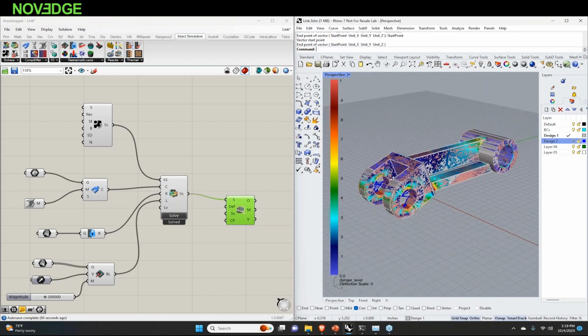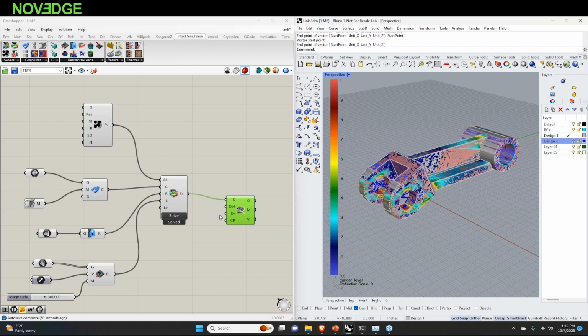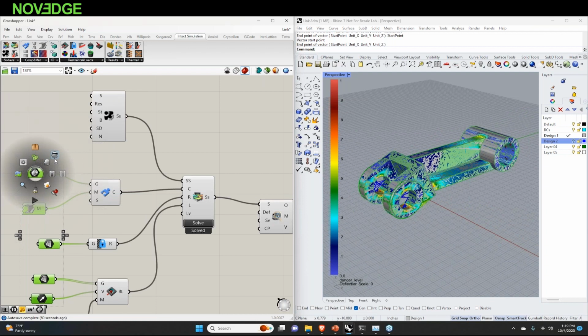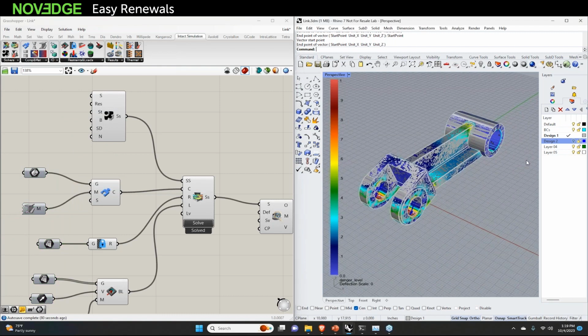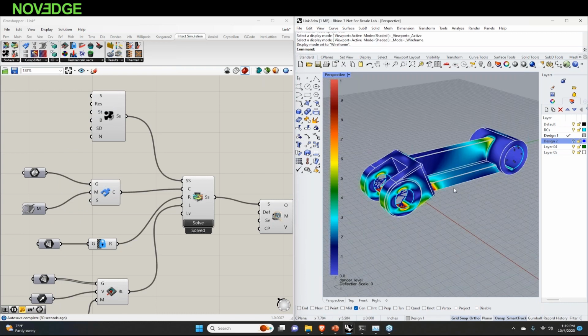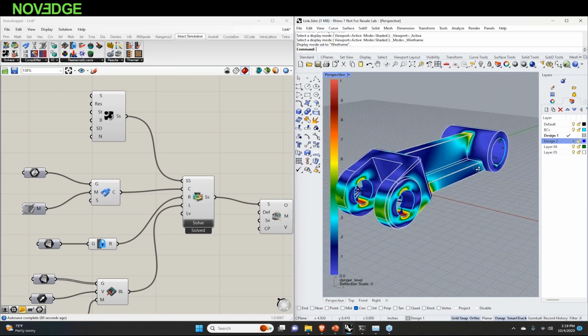And on the right, you see the danger level being displayed on the geometry. What we've also got, it's just an artifact of Grasshopper and Z, we've got some Z fighting going on. So I'm going to turn off the Grasshopper display of the geometry that is participating in the simulation. And I'll also switch to a wireframe view. So now we can see the results here.